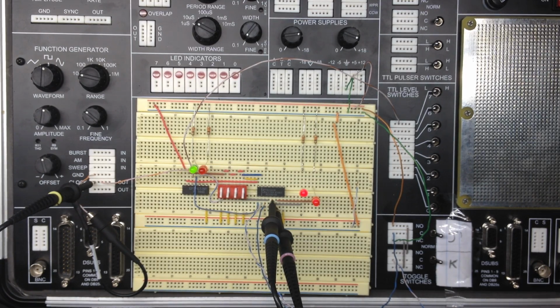The J and K switches are currently set to high. When we look at our truth table for how the JK flip-flop is supposed to work, whenever J and K are set to high and our preset and clear are set to high, we should receive a toggling output, which is what we're seeing with the LEDs at the moment, that are constantly flipping back and forth between one on and the other off, and vice versa.